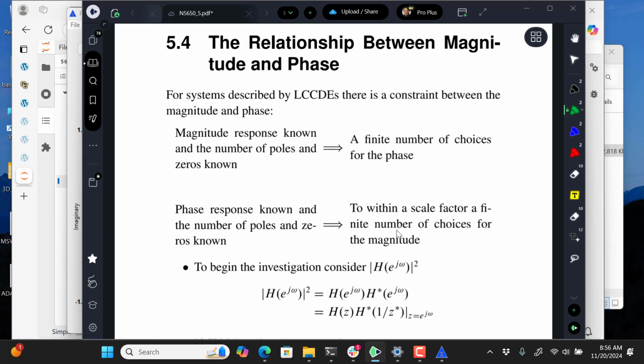You remember that from somewhere in microcontrollers or something, just right shifting. Right shifting is like a great thing. Divide by 2. It's too much work to do an actual division most of the time, but you can divide by 2 by right shifting, and that's used a lot in real-time implementations.